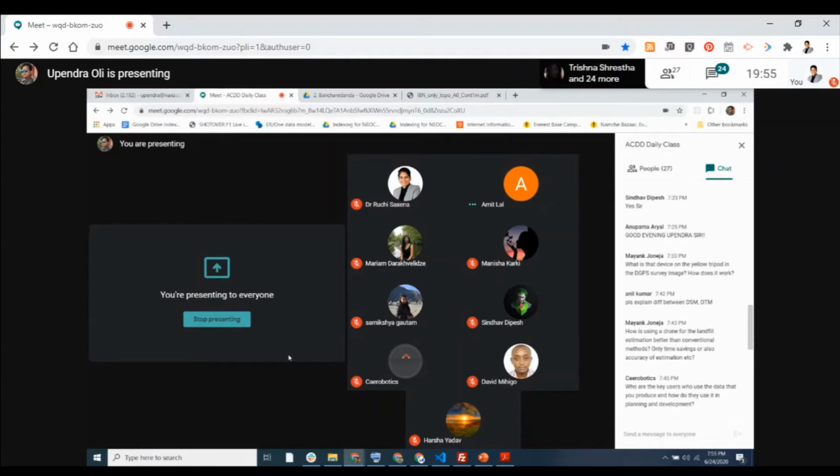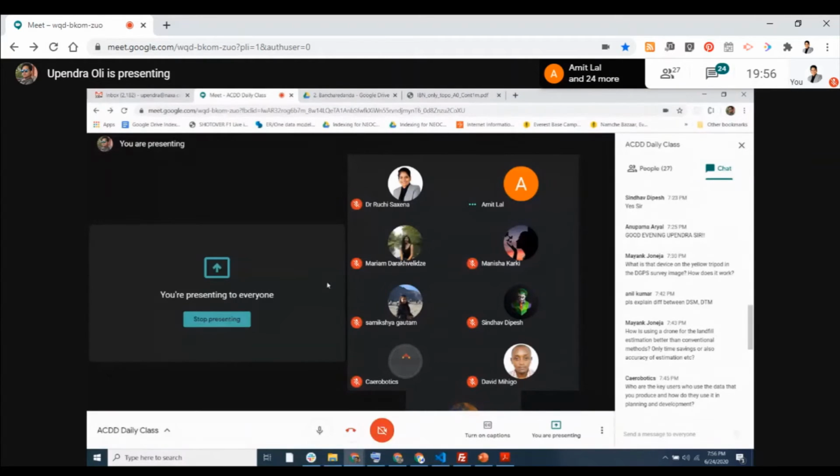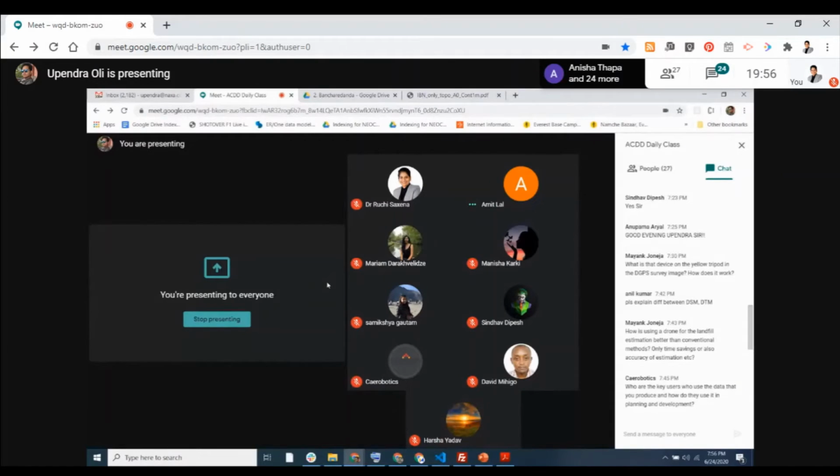Yeah, you might say that, but it's not completely true. GCPs from DGPS are used to orient the direction of the model and to accurately position it in the XY plane. The model can be generated without the DGPS, but it would not be accurately oriented. It can be shifted in the XY direction or rotated in the plane. To remove such errors and problems in the model, we use DGPS coordinates.